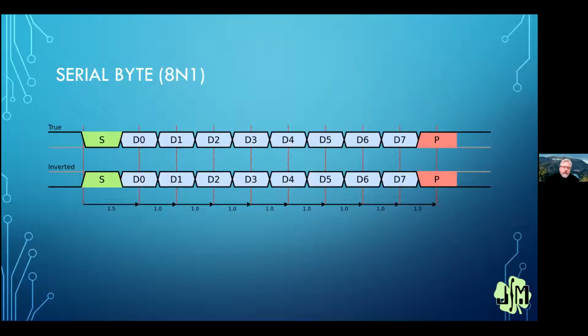They were hitting these funky numbers. And I remember when the guys at XP were telling us at the laser tag about that, and they said, this could be a problem, so you may want to use a slower data rate. I said, no, it's no problem. I can adjust the baud rate to the exact rate coming out of the XP or going into the XP, because of course we are not using hardware baud rate generation, traditional baud rate generators. So we can have any baud rate we want.